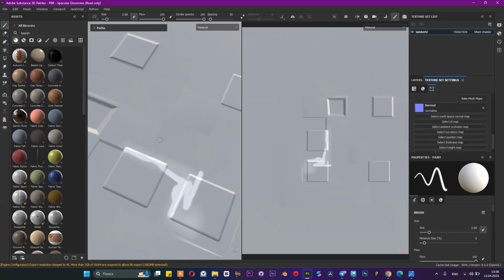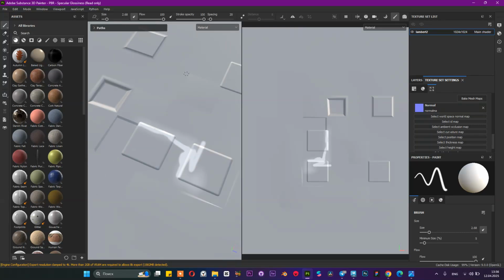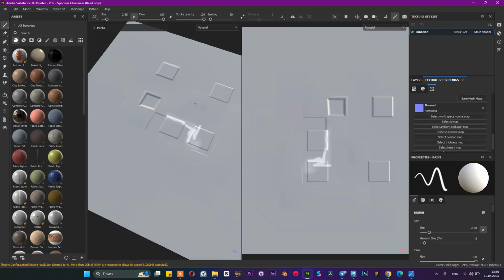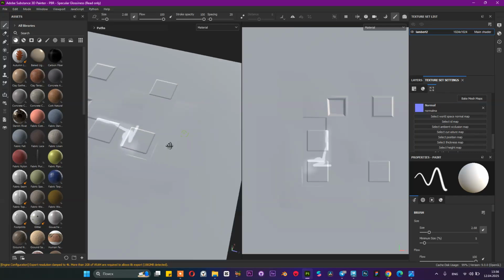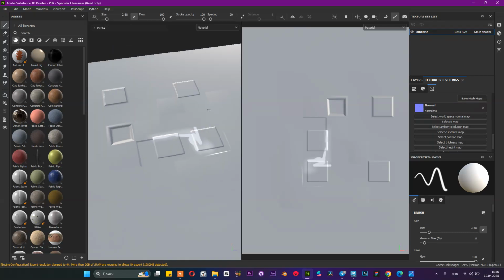Okay, this is a pipeline when you work with low poly and high poly details. It can be used on roofs when you have a lot of bricks on it. You can model on the high poly, and if you have time, you can bake it on the low poly roof. And you will get this nice texture normal map and keep your environment with a lower polygon count but with high quality details. And this is a useful pipeline.